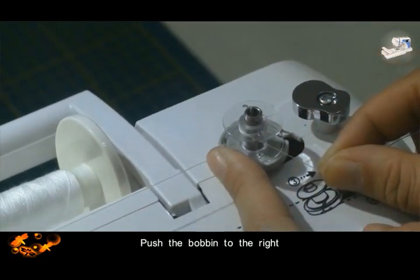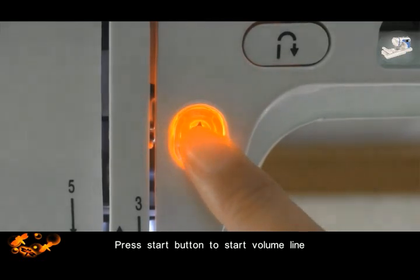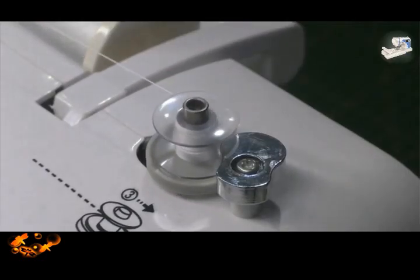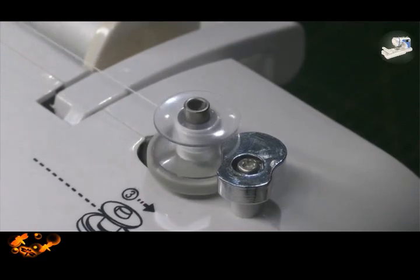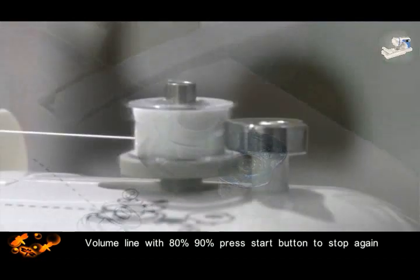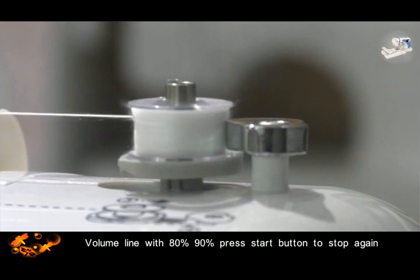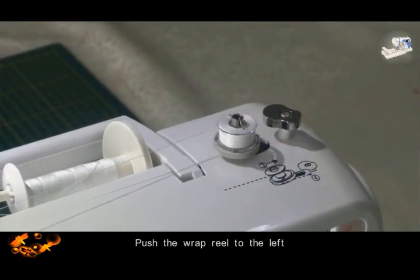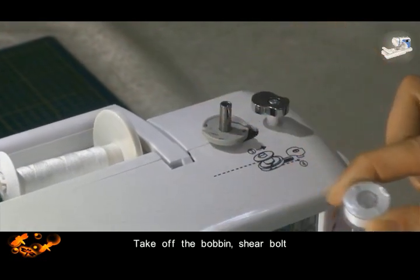Push the bobbin to the right. Press the start button to start winding the thread. Wind to 80%, 90%. Press the start button again to stop. Push the winding reel to the left. Take off the bobbin and cut the thread.